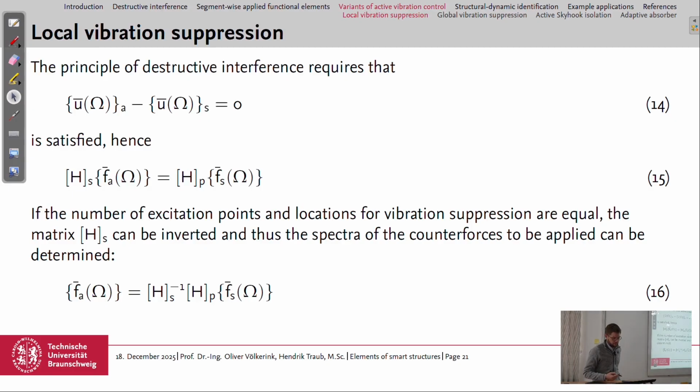And if the number of excitation points and the locations of vibration suppression are equal, then we can invert this matrix and calculate directly the vector of forces we need to quieten the structure.